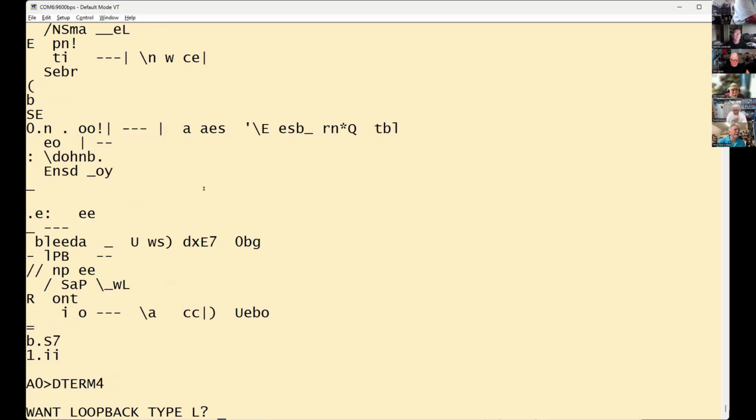Well, actually, what baud rate are you running? Well, Walt, I've tried it from 300 baud. What baud rate are you running right now? Well, that was the utility port. Port 12 and 13 is at 9600 baud. Your BASIC program will not run at 9600. Drop it down to 300. Right, but I've done that.